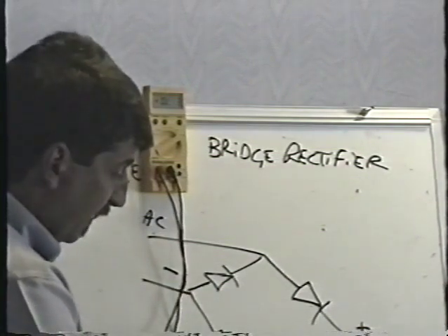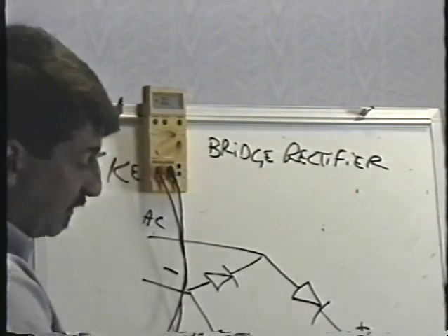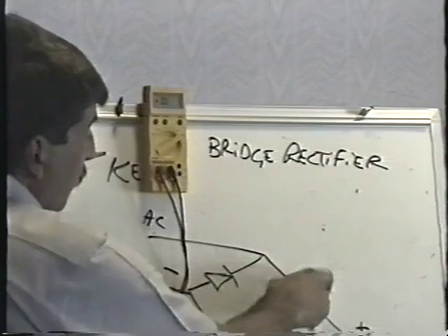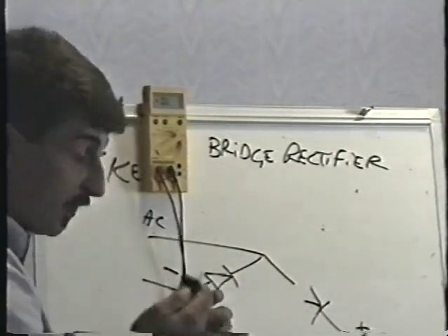I get an open reading there. Open reading both ways on that one. One of these diodes is open. I'm getting an open reading both ways. The diode's open, which is pretty unusual. Usually they short circuit.